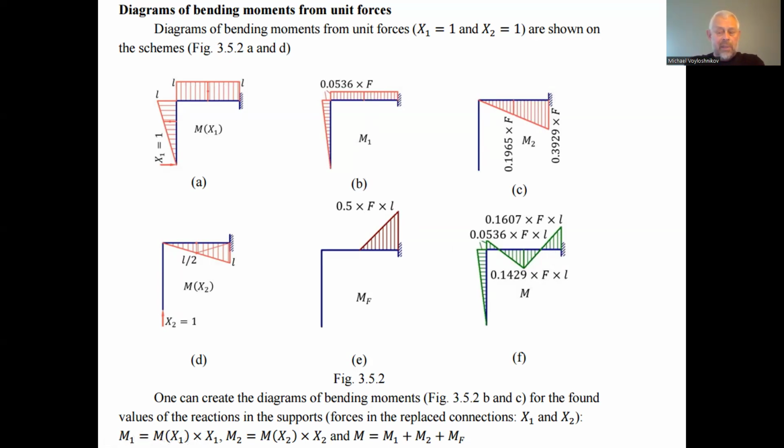So for a definite assignment, we just have to remember the direction of application of the shearing forces and bending moments we use as positive. Usually in mechanics, we use as positive bending moments rotating the mechanical system counterclockwise. But for a definite decision, perhaps for positive we can take the clockwise rotation of the system.